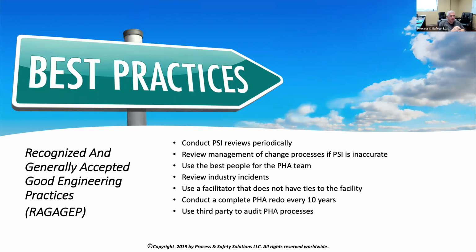You can look at it and say that, well, there just was not a lot of effort, there was not a lot of knowledge applied to the PHA, and the methodologies that have been developed since then, and known hazards that have come about since then, weren't applied. So if we're only doing a revalidation of the initial, then we can't capture all of those new hazards that we have been able to find from the time of the initial till now.